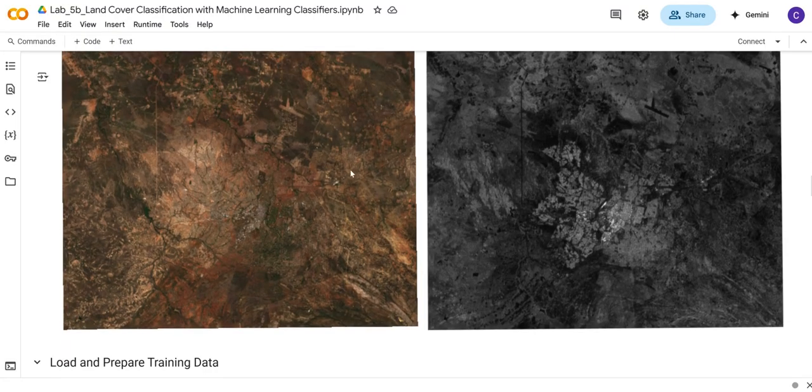But these two imagery, the optical and the ALOS SAR dataset, really complement each other, because for the cases of the bare areas or the cropland areas, the backscatter values are quite different from the built-up areas. This is important when we want to minimize the spectral confusion between classes that may appear similar, in this case the bare areas and the built-up areas or cropland areas.